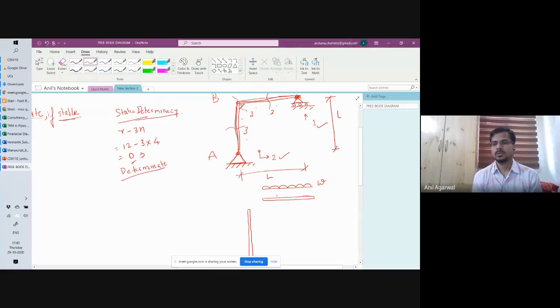Fine. So this W is acting on this member. What kind of forces can you have? You can have a vertical reaction here, that is this support C. At B, you may have a vertical reaction too. Correct? That is the 3 unknown forces at location B. This is one unknown force. Then there may be another unknown force, and there may be a moment acting here. Fine.